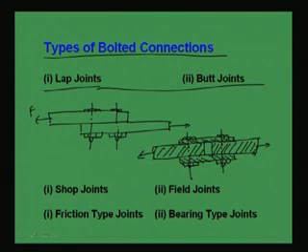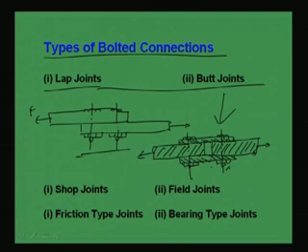Okay. So, butt joint will be looking like this, that two plates are joined through this extra plate and bolting has been done here. One bolt per joint, two bolts per joint, because minimum two bolts will be required for this butt joint, and here one bolt is minimum and two also we can provide. As per the design requirement, we have to decide the number.